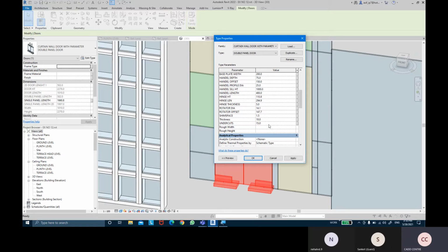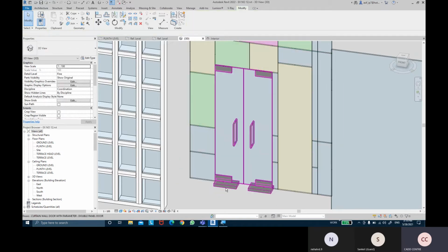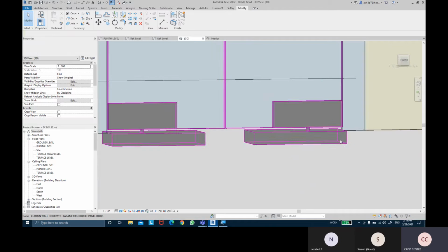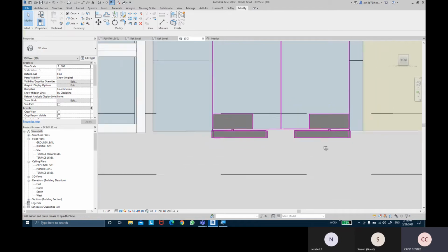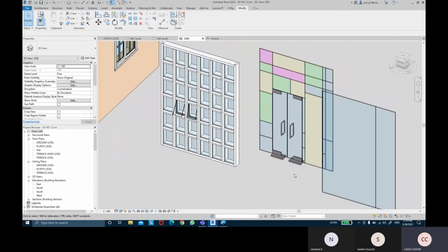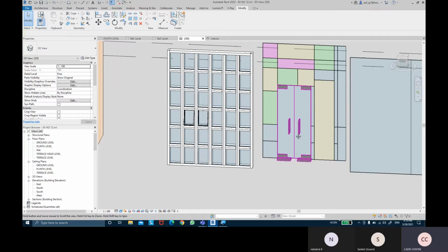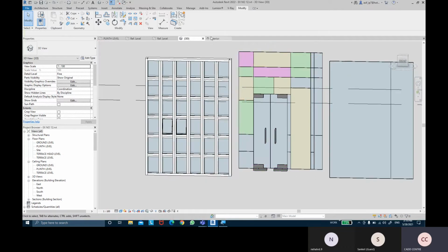Okay, maybe I'm going to do a 15 mm undercut of the door for this double panel door. Actually, it's gonna have 15 mm of offset from the base. Totally parametrical, controllable glass door. Okay, so we applied it.